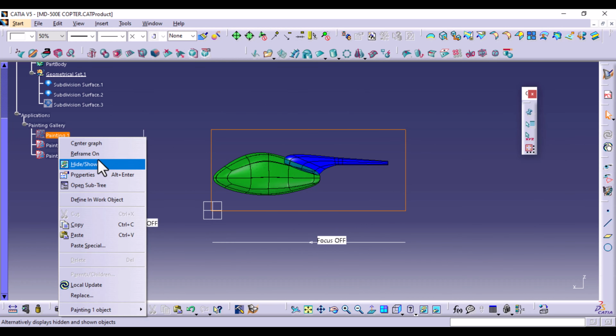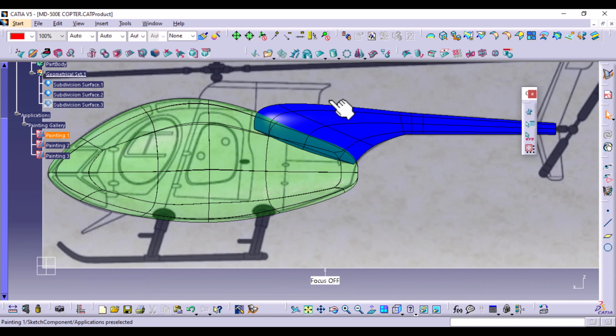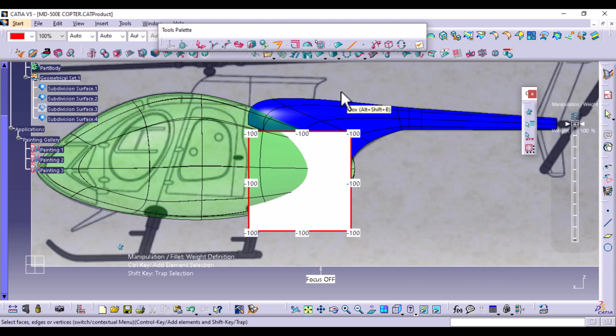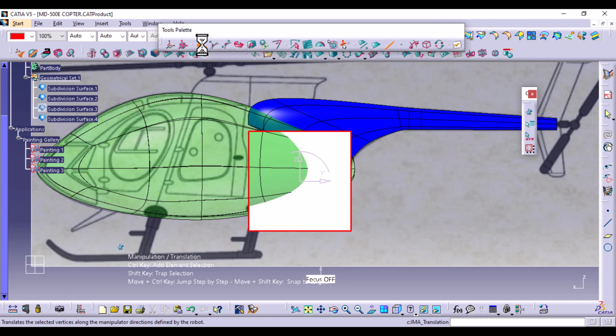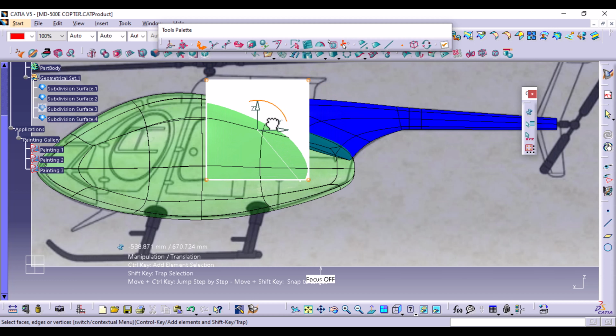So now we can create this top profile, this housing for the main rotor right there. We start with the box primitive. So from this option, you can select a box, and then you can translate this box, select vertices instead. You can translate it to this position.